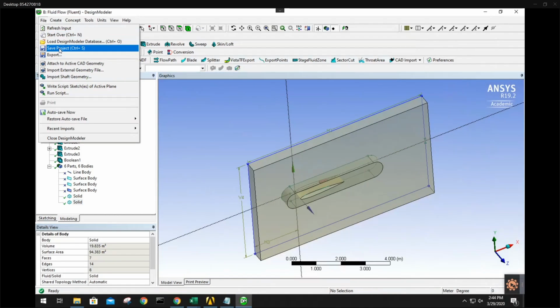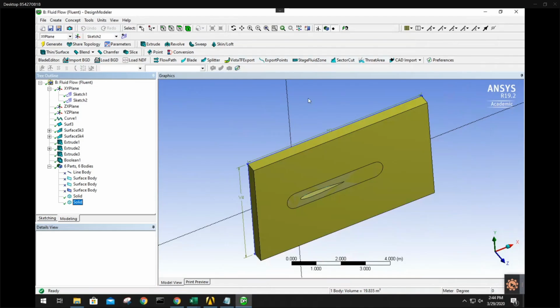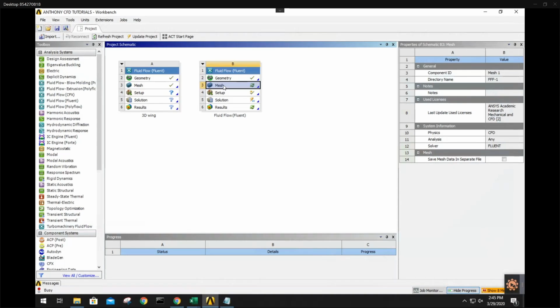As a preface, this is a rougher CFD simulation. In general, if you want to do the most accurate possible, you should avoid wall functions, and you should try keeping with K omega SST. But as I showed in that Start CCM video, K omega is the most accurate.